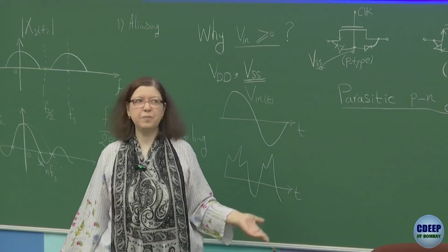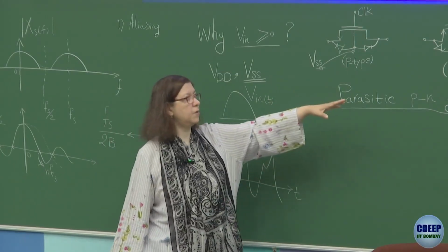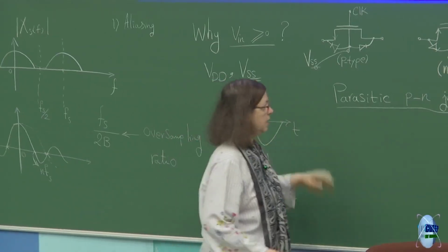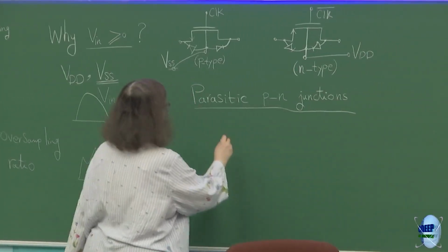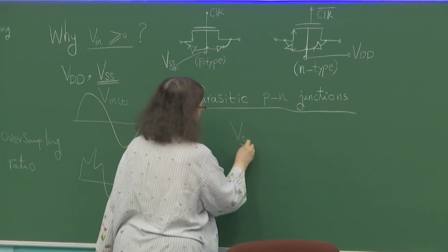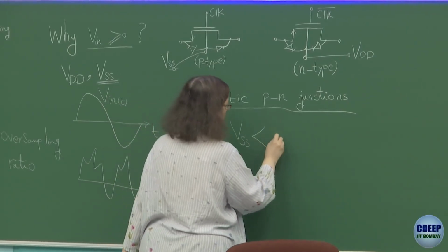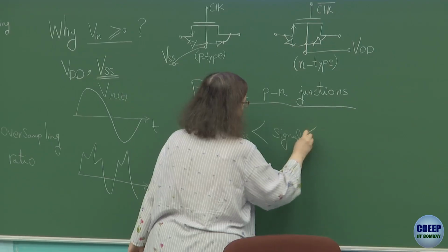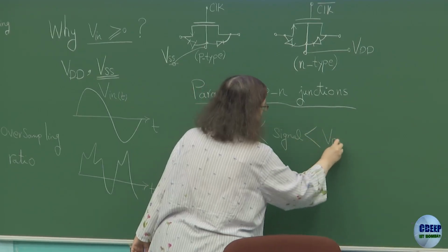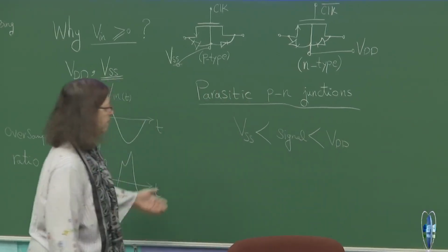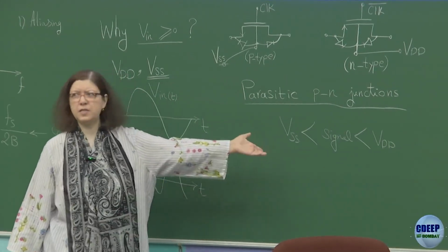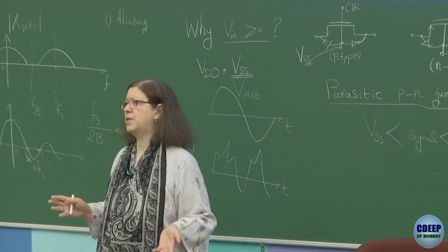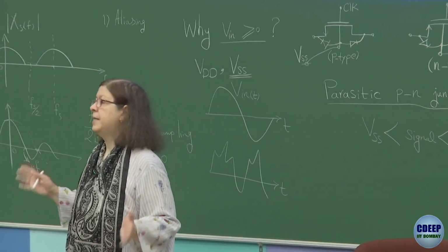It is not possible for any of these four diodes, with this condition and with signals which are within the range of the supply. I just write in general any kind of signal in the circuit. If I put this condition, they can be very close to VSS, very close to VDD, but within this range. It is impossible for these diodes to turn on, right?